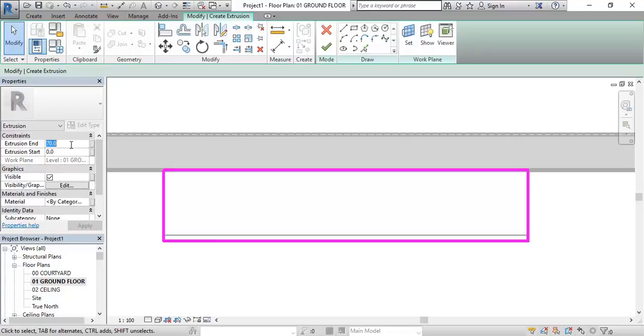And then the height. So what height would you normally make your vanities? 900. Yeah, that's if you want a high one. You could do it that high. That's quite high. That's the kitchen benches. That'd be the basin height. Yeah, you can try to do that height. Usually you make vanities a bit lower than typical benches.